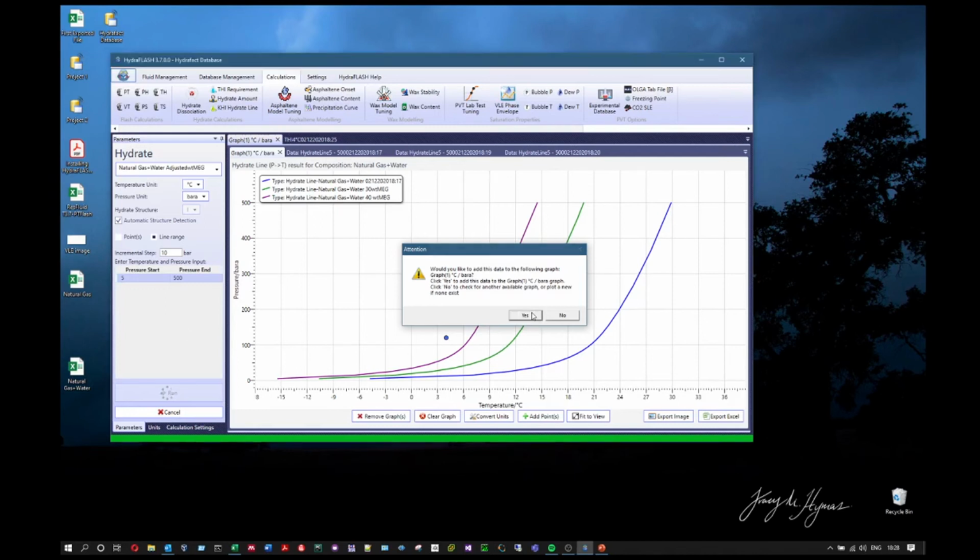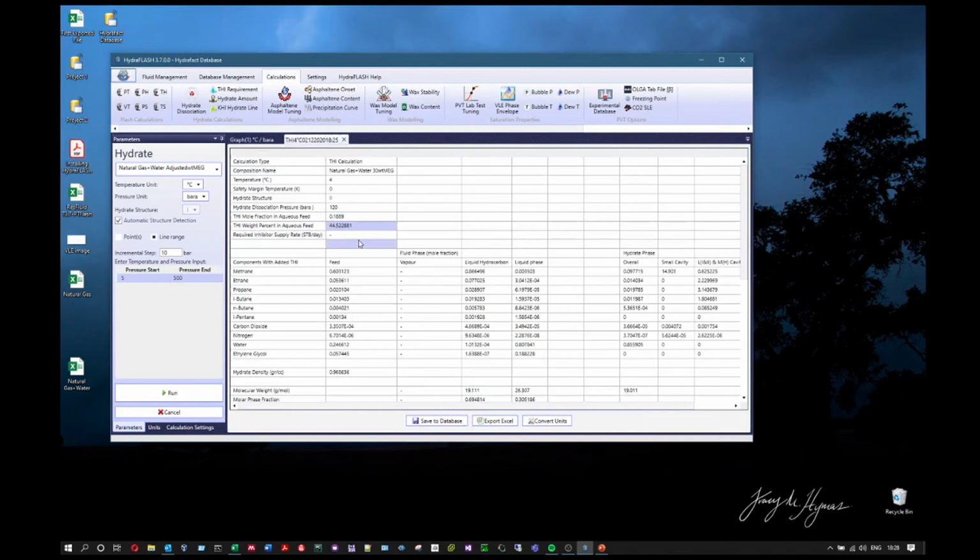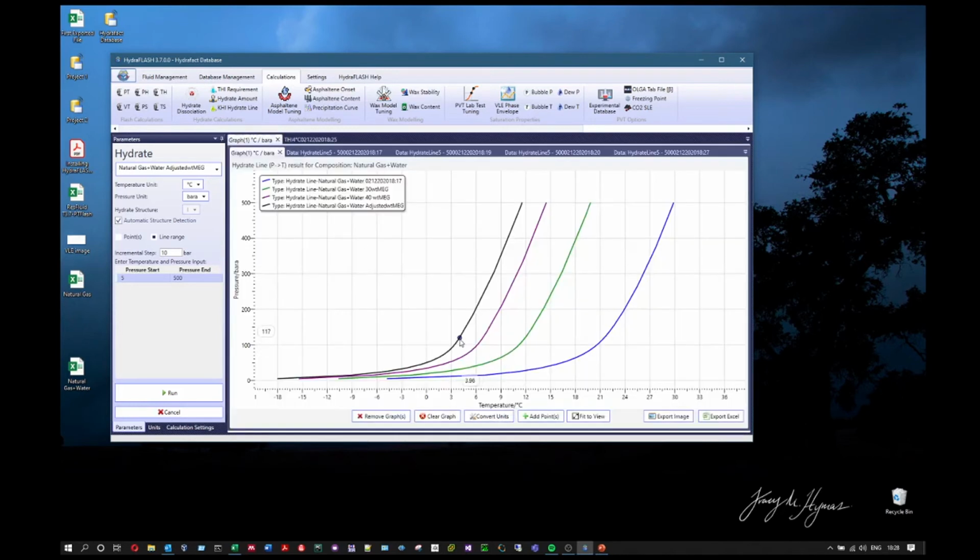Okay, now yes. Now, as you can see, the hydrate phase boundary falls exactly on my operating conditions. So instead of gradually adding a little bit of MEG and then seeing where I am, and trying so many hydrate phase boundaries, with one single calculation entering the working conditions, it told me that you need 44% MEG to work exactly on the hydrate phase boundary.